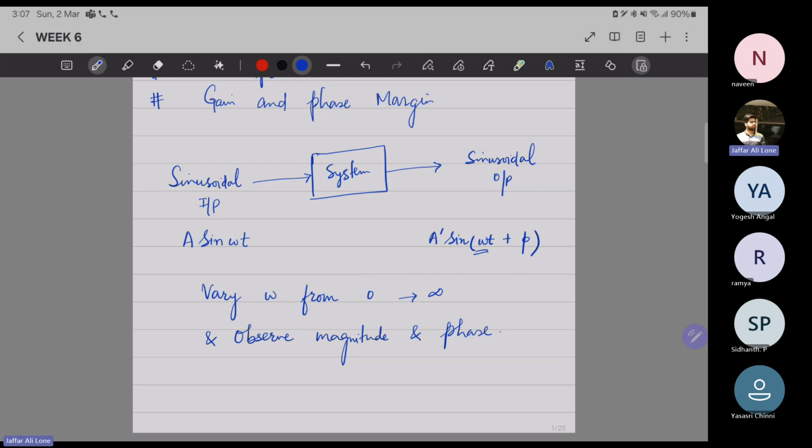This has its own advantages, because in time domain analysis, if your order increases, it becomes very difficult to study those systems. Similarly, we were not able to study relative stability in time domain analysis, or even if we do, it's very easy in frequency domain analysis, as we'll be seeing when we study polar plots, Nyquist plots or even Bode plots.